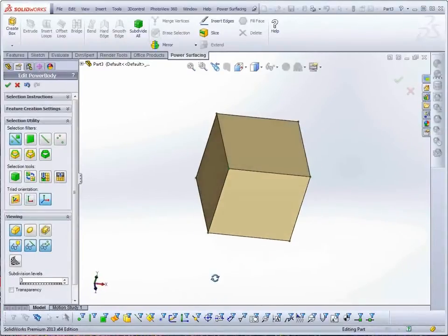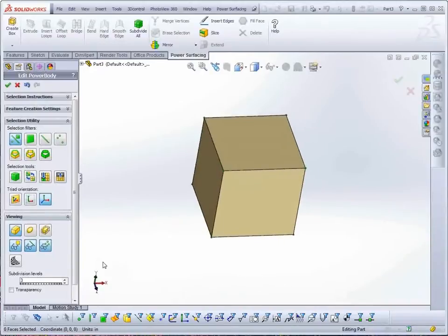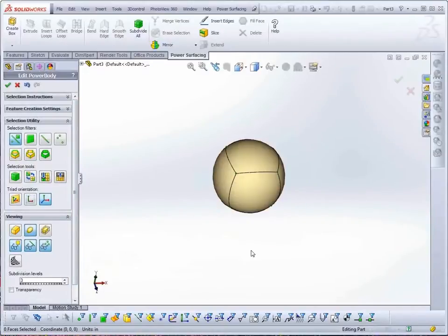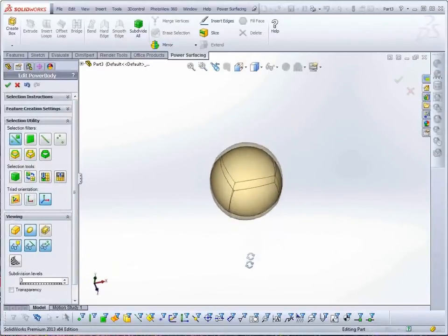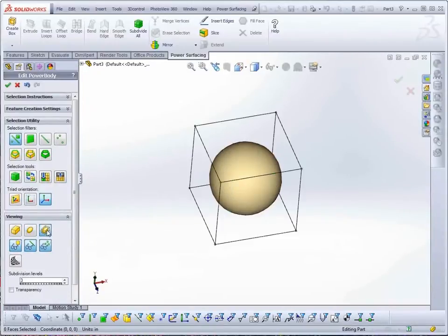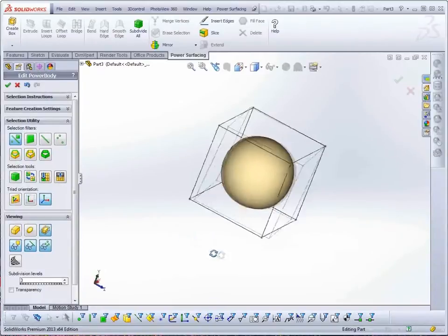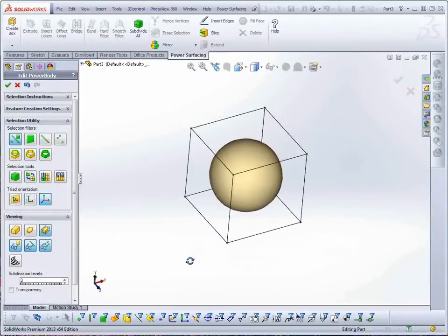With Control, the control mesh shows the base object that is used to create the sub-D model. Sub-D stands for subdivision surface. The Sub-D display mode shows the subdivided model along with the control mesh's edges and their new locations. The default display, Sub-D plus Cage, gives you the best of both while the model is still very simple.